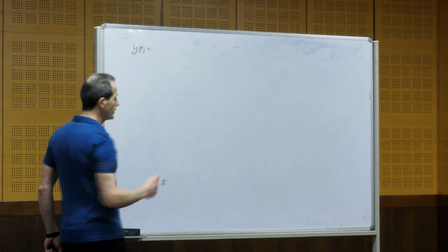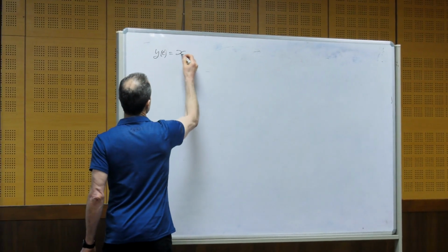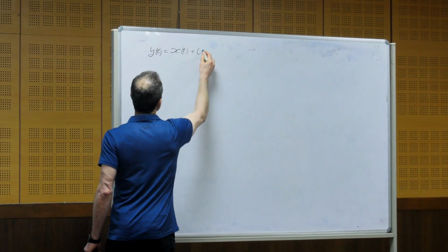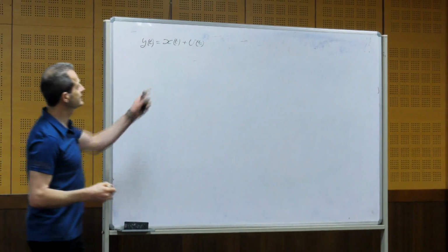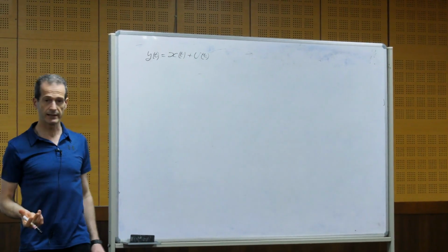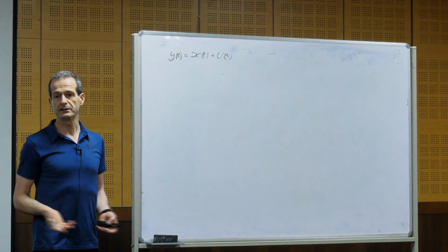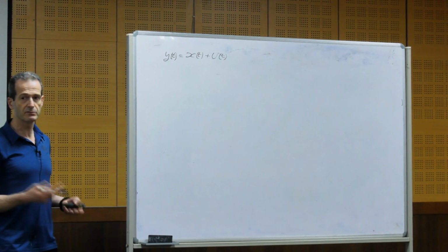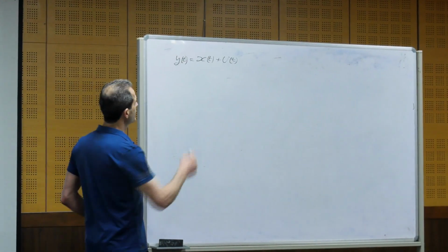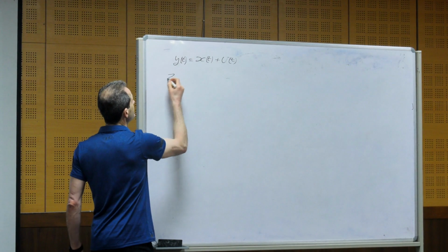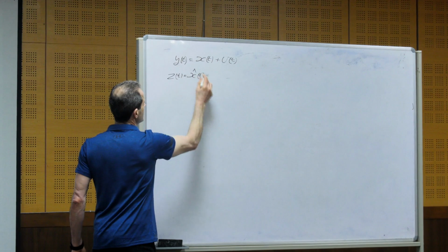Our model contains a desired signal x(t) plus noise v(t). We know that the signal and the noise are uncorrelated. We can say even statistically independent, but for the Wiener filter, it's enough that they are uncorrelated. Then we wanted to find an estimate z(t) of the sample x(t) at time t